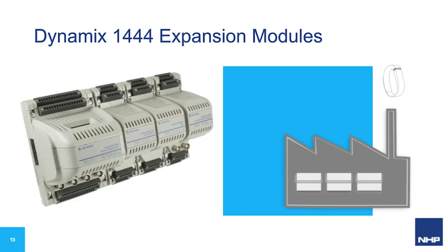The device has Ethernet connections. They're located on the top of the module. This allows for easily expanding your system. And we also have some expansion I/O that we can apply locally. So we've got an analog output, if you did need to get something to an existing DCS or control system, or a relay expansion module for expanding your interlocks, and then a tachometer. Tachometer is important because sometimes when you're doing variable speed applications, you need a way of actually getting the base speed. So we've got those as expansion modules, and we can essentially provide those.